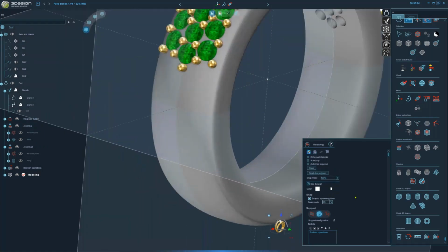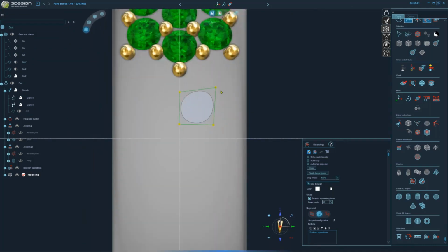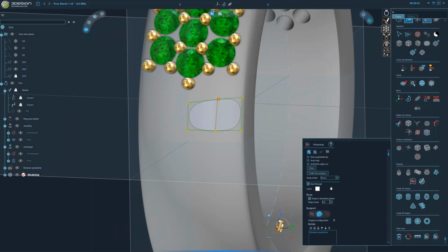Okay. So the way this tool works is now when we, instead of starting with a solid figure or even a flat figure, we're going to draw the mesh directly on this surface. So we'd start with drawing a square. Go flat here so I can start to even this out as I'm going. Okay, so I can continue to draw just by connect the dots here. Go over to the corner, and as you connect the dots, it's going to fill in the next square. So you can definitely do it that way and just draw everything one square at a time, but you may want to edit these. So we're going to switch modes again.